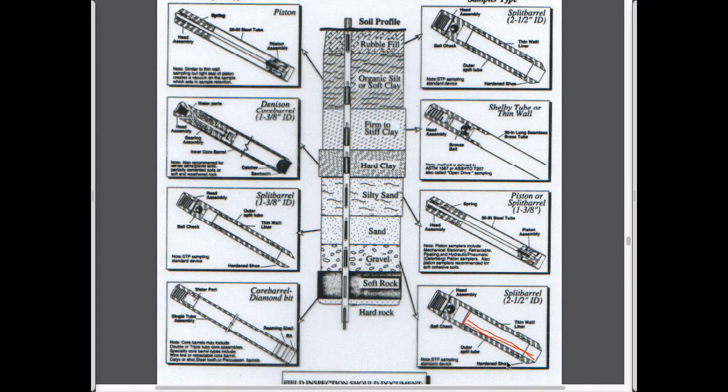And so for coarse materials like gravels and sands, you'll have a thick wall sampler, you'll bang into it, get it onto the surface, you break it in half by taking the shoe off, taking the back end off, and the middle parts between those are just two halves of a cylinder that open up and allow you to take your sample out. And so that's kind of the generic sampling type for coarse sands. Things that don't have cohesion.